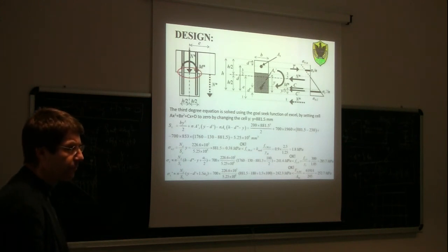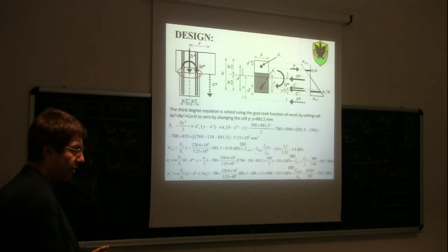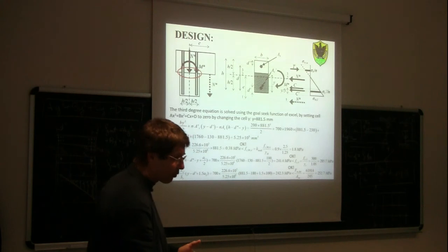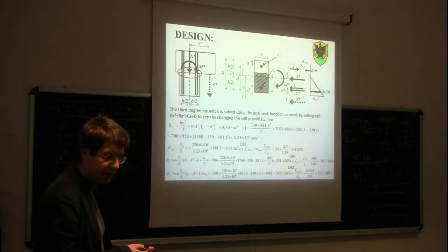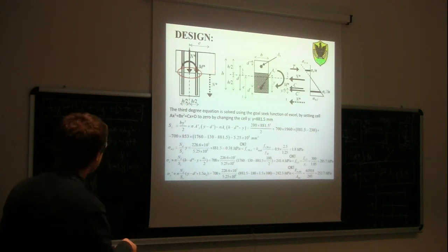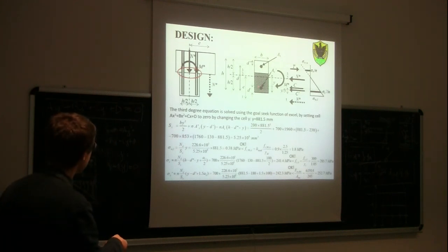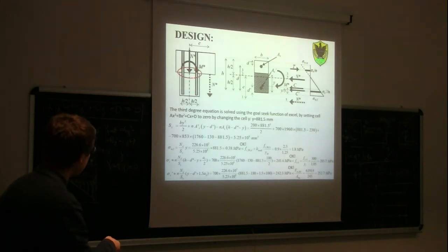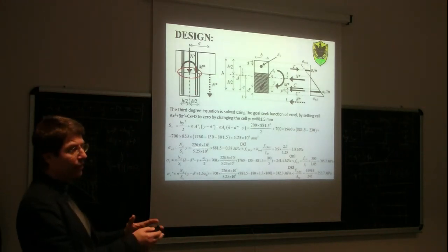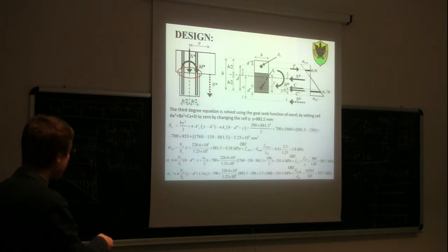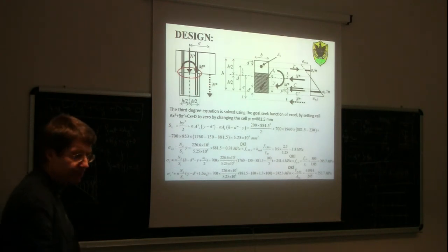But as you said before, this would be a failure for buckling. So this is the right comment. If the bar is going to buckle, it's also going to break the wood. Where is it going to break? This wood here, parallel to the grain, or this wood here perpendicular to the grain? It's probably going to buckle here. So this buckling of the steel will occur simultaneously with the failure for splitting of wood, splitting perpendicular to the grain. After that, probably it is going to break, that's it.